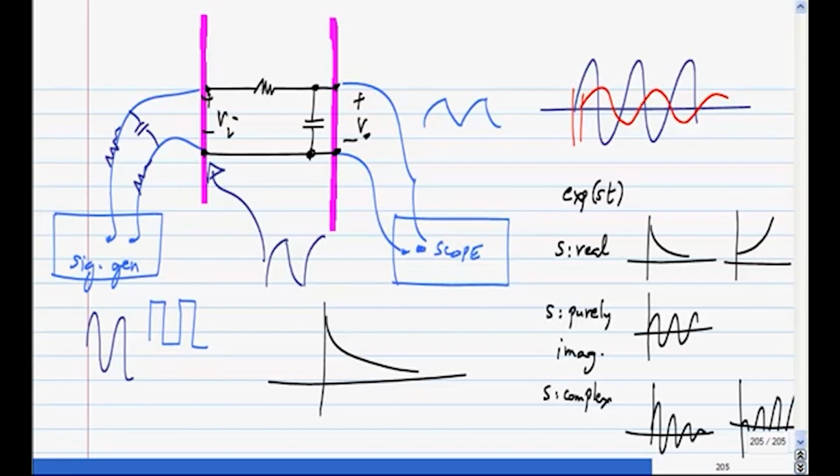And also, we are measuring the steady state response, right? So what it means is that in the sinusoidal steady state response, you apply a sinusoid. It's not that immediately you get a sinusoid as the output. At the beginning, it will have the exponentials also, which are part of the natural response of the system. But for any stable system, the natural response parts will die out and the forced response will stay.